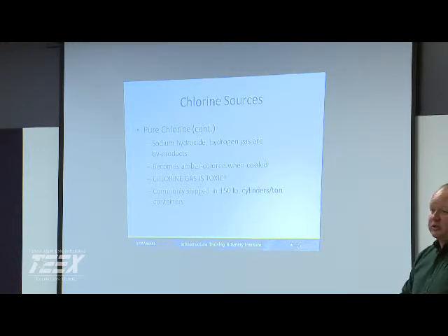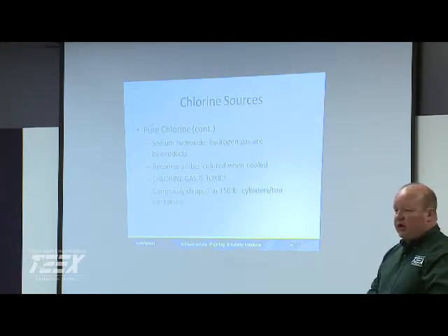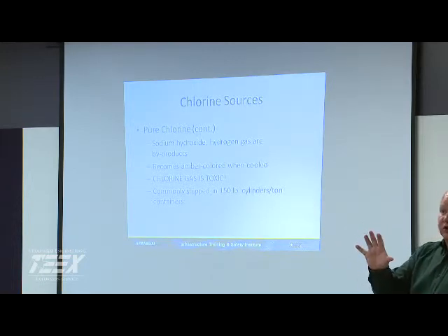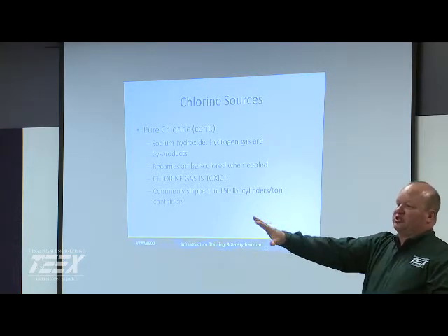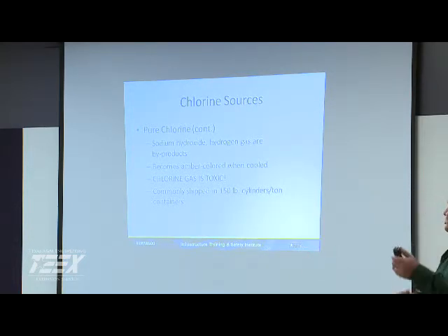Proper ventilation is a big thing. Forced ventilation from the top and being able to ventilate it out. I don't know if y'all have any kind of chlorine leak detectors or something like that. Handheld meters. Those are real important components. If you can walk up and tell that you've got a problem before you have to go in, that's really nice. We had an issue where they designed a facility.